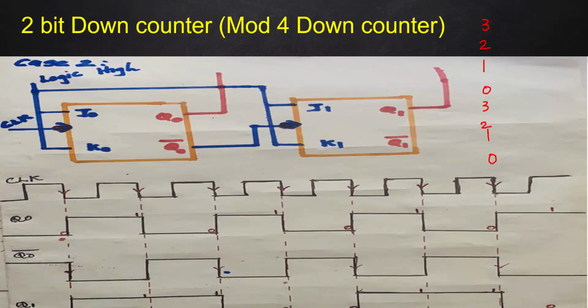All the other connections are the same as in up counting, and in order to convert this into down counting fashion, you have to change the clock. Instead of considering this Q0 as the clock of this flip-flop, you need to consider the Q bar output of the first flip-flop as the clock of your next one. Then it will work as down counting.